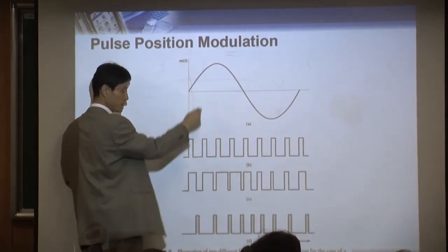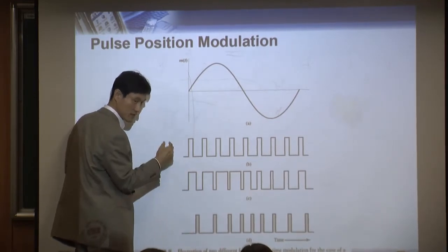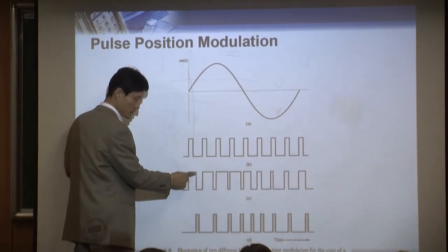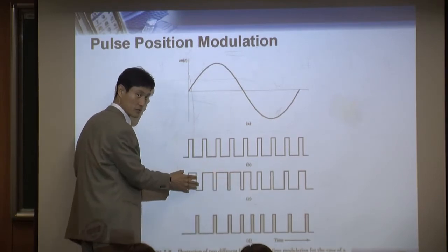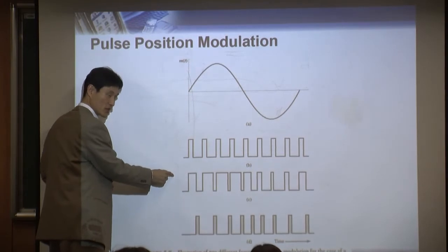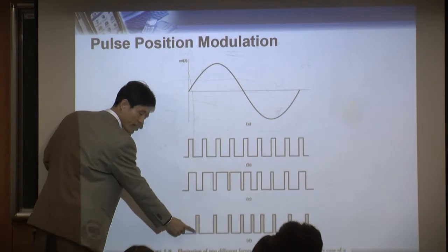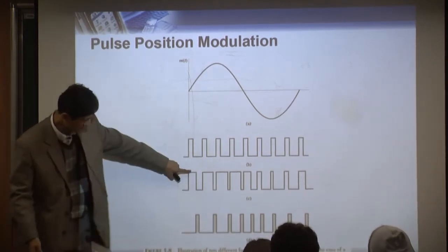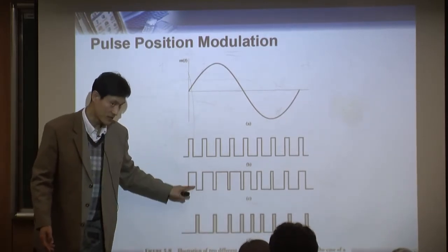If the message goes up, now falling edge is a little bit delayed because the width is large, because the pulse needs to be fat. So this falling edge are now in a different position. That's what happened in the pulse width modulation, right? So every time that this pulse width modulation has a falling edge, at that position, you're going to have rising edge in PPM. So look at here. This falling edge and rising edge same at same time.